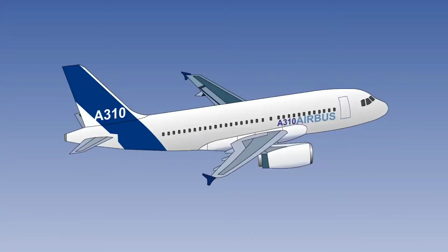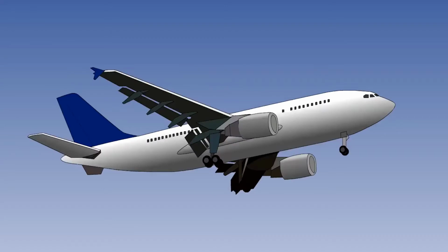Modern, high-speed jet transport aircraft have swept wings with relatively low thickness-chord ratios. For example, the Airbus A310 has a ratio of 12%. The overall value of CLmax for these wings is fairly low, and the clean stalling speed therefore correspondingly high. To reduce the takeoff and landing speeds and distances, various high-lift devices are used, increasing the value of CLmax.